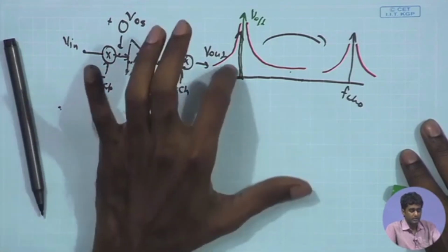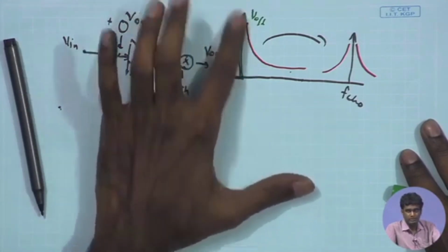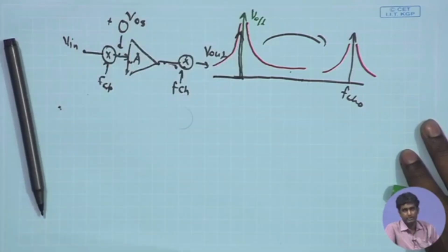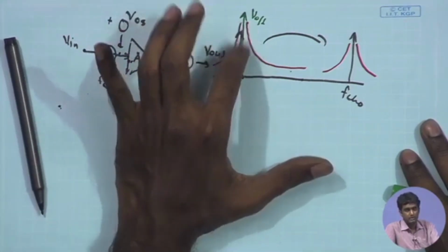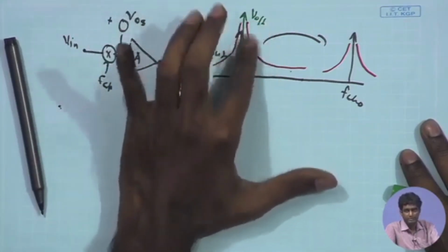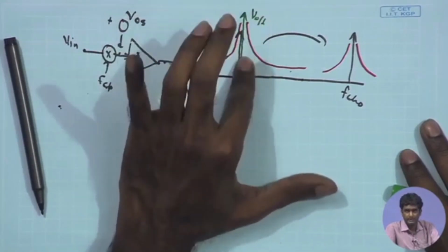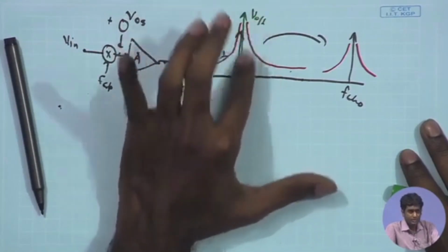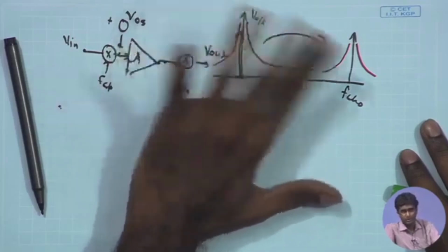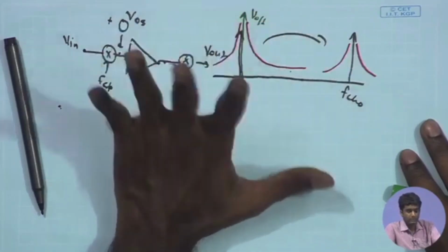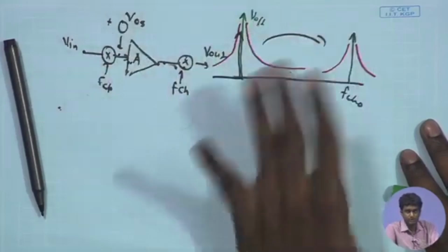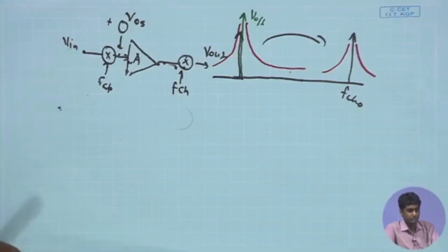Of course, in our case we are not concerned with the DC level of the signal, we are anyway trying to reject the low frequency content, because you are having noise etc., and dynamic offset that we will see just now. But in case of the overall transfer function, it may be important to consider that the offset signal also gets shifted to high frequency because of the chopping operation.